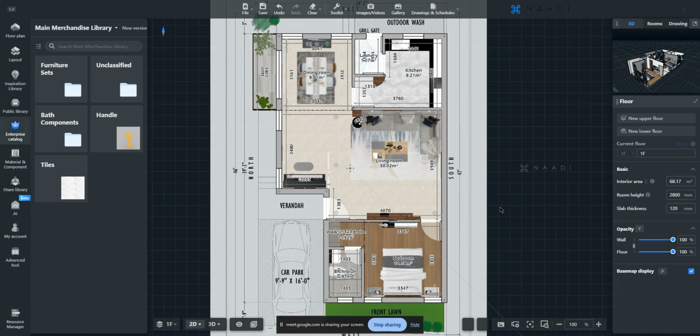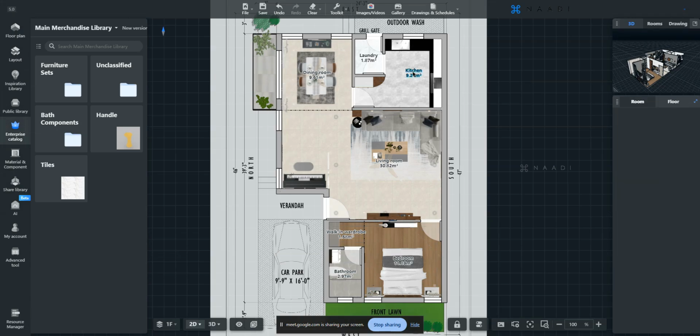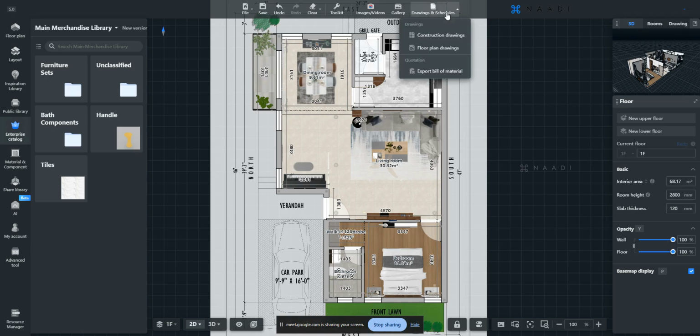In the plan view, by selecting that space, you would have provided a room type and room name. Here, this room name, what you typed, is something that will get reflected in your drawings. So make sure this room name is properly mentioned for each and every space. If you want to mention something as master bedroom or main bedroom, anything of that sort, just add it in the room name. Make it proper in the model, so that in your 2D drawings that will be automatically updated.